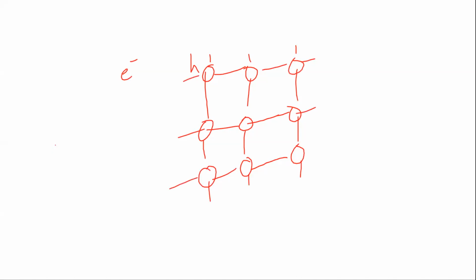If it is n-type, what is going to happen? There is an extra electron. When I say extra electron, remember the covalent bond. This extra electron in n-type is not a part of a covalent bond. So it's very easy, you can just give a small energy and free up this electron, and it can conduct from one place to another place.